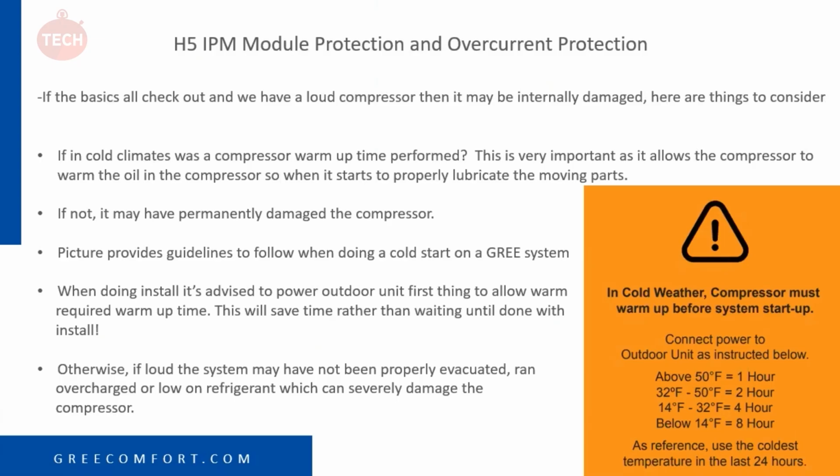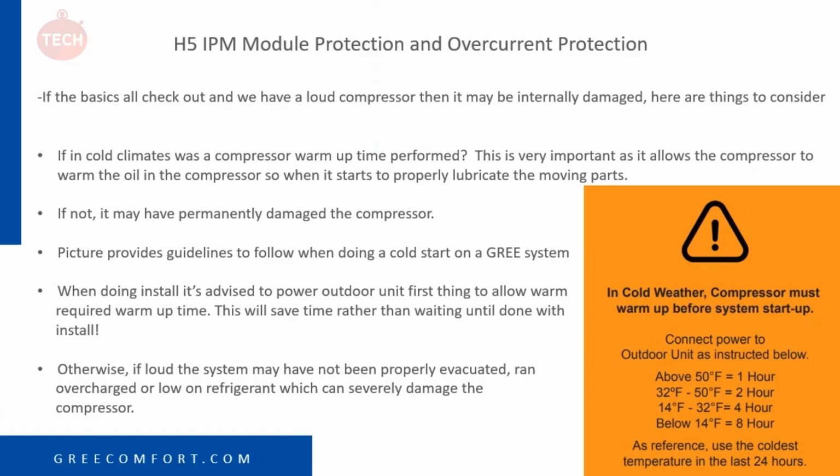So if it's above 50, you'd at least want to have that. Now we're going by the coldest temperature in the last 24 hours, so something to consider. So again, coldest temperature in the last 24 hours, say if it's 50 degrees or above, we need 1 hour of compressor warm-up. 32 degrees to 50, we'd want a 2-hour warm-up. 14 to 32, we want a 4-hour warm-up. And below 14 degrees, we want an 8-hour warm-up.